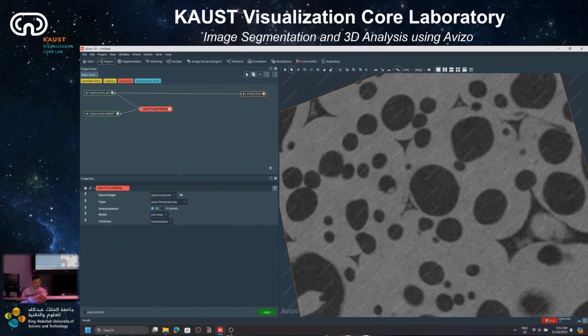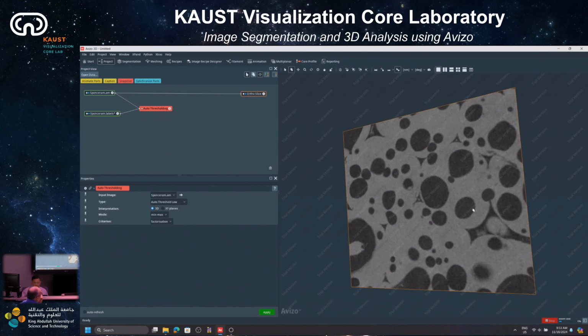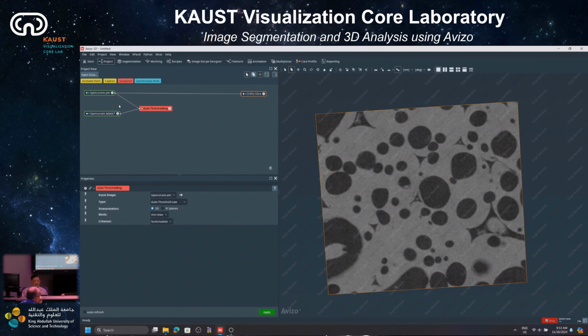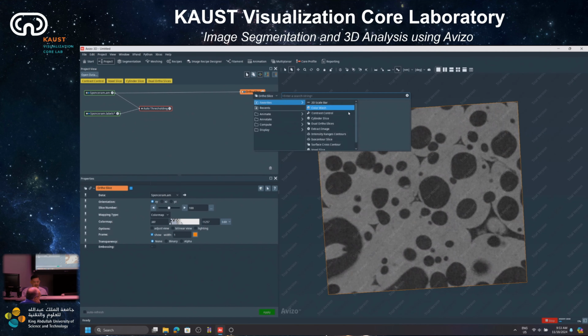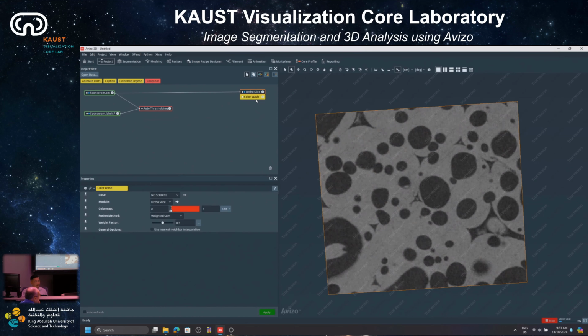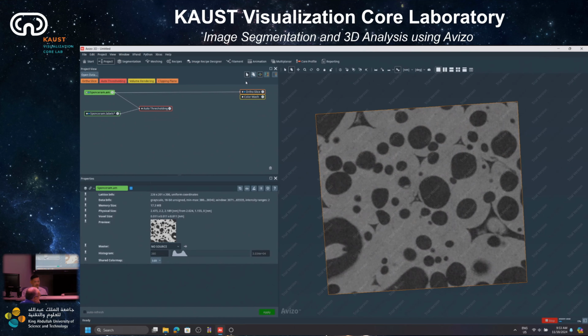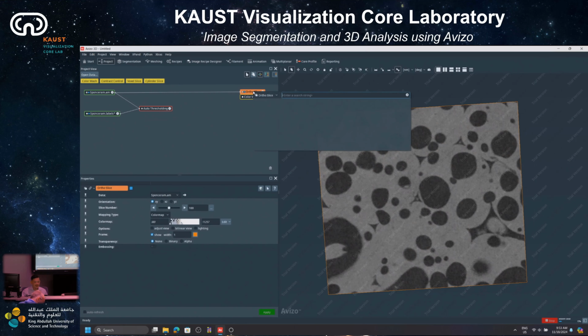And here, because I use ortho slice just to visualize the result. So in the ortho slice of the original data, the grayscale one, you can right click on the ortho slice, and you can see the second on the list is colorwash. Click on colorwash and create, or double click. So the initial dataset attaches the ortho slice, and on the ortho slice module, right click and attach colorwash.